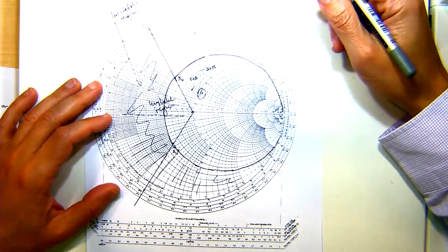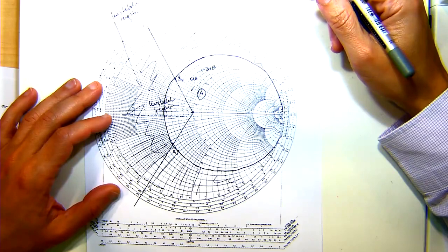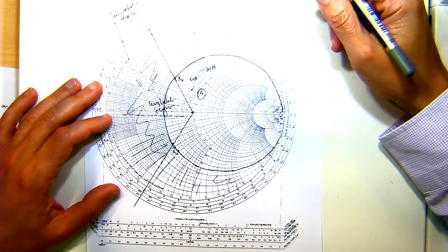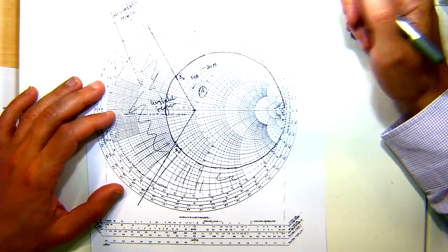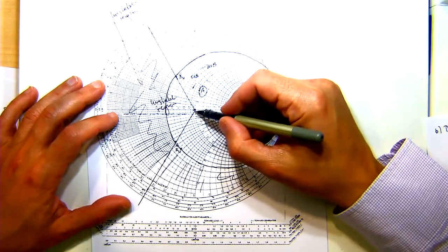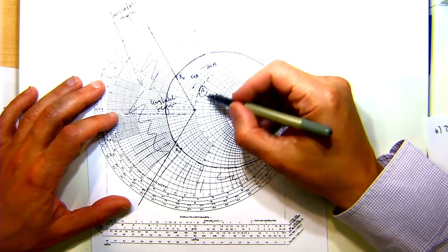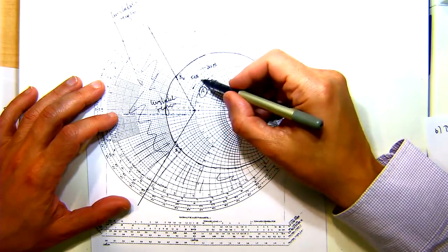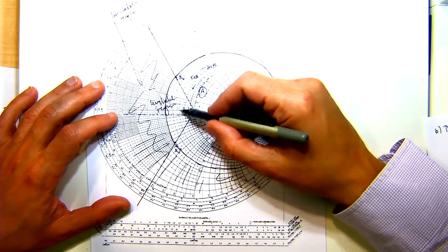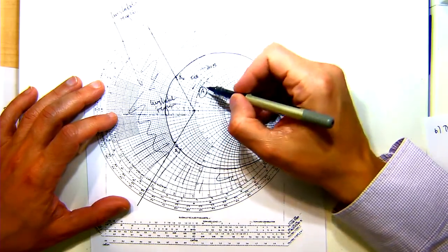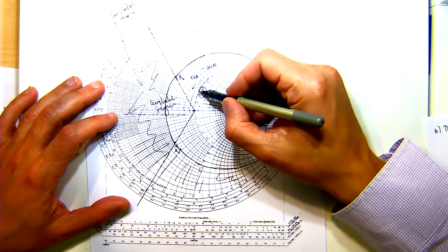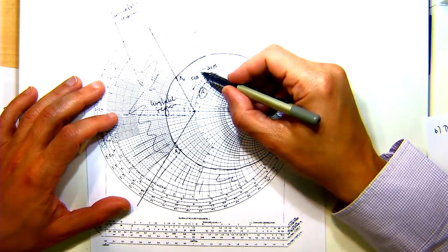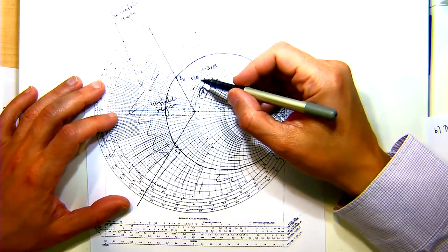Could you just go through again how you determine A? Because the biggest resistive part, isn't it meant to be close to infinity? No, because remember the resistive part is these lines, right? These are the circles, right? So if I'm on the 3dB circle, anything here is less resistance, less resistance, less resistance. But why don't we go further to the right? Because you can't, because it's the 3dB gain. Oh, you can choose a lower gain. Like the 3, oh, okay. Yeah, sure. Okay. All right.